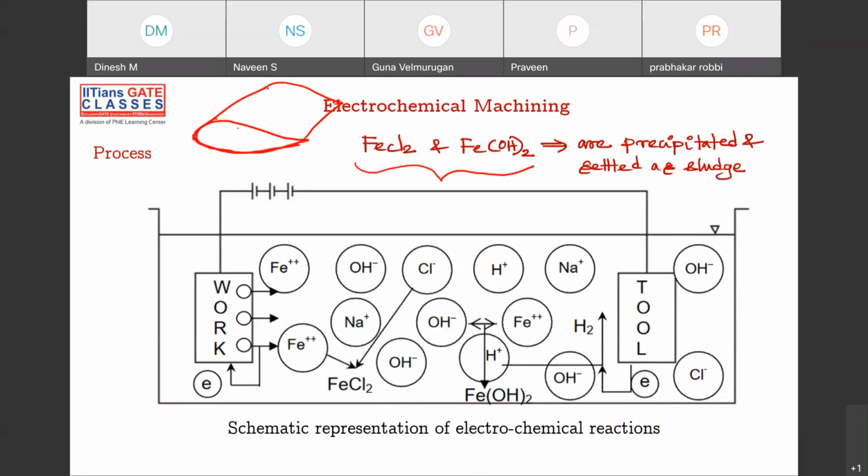If this aerofoil shape you want to manufacture, what you do, you have a negative aerofoil structure on the tool, and this kind of structure is formed on the workpiece here. Understood? So this structure is given to the tool itself. The tool will try to get some chemical reaction. This workpiece is converted into like this. Is it okay?